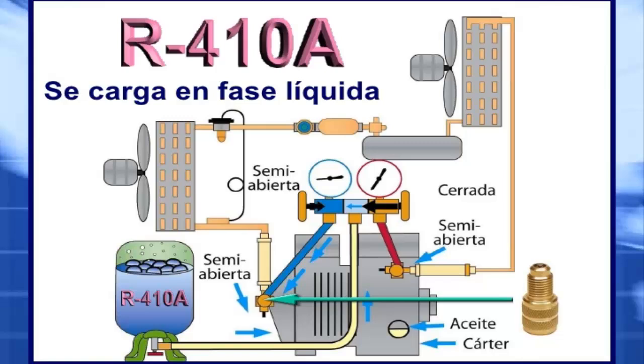I. Remember to charge R410A in its liquid phase until reaching a stable low side pressure. Then, measure the system's power consumption to ensure it does not exceed the manufacturer's recommended levels.